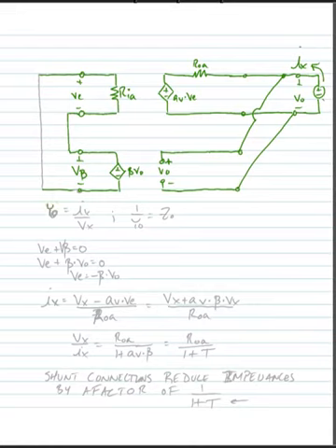Alright, and actually what we're going to do is find the conductance, because it's easier to find conductances when we're looking at shunt circuitry. So we're going to find Yo is equal to Ix over Vx, and note that the inverse of that is equal to the output resistance.